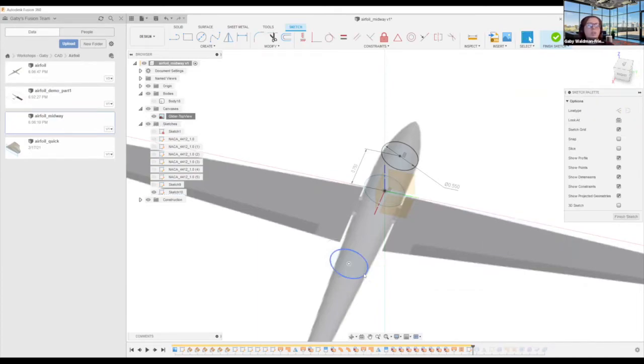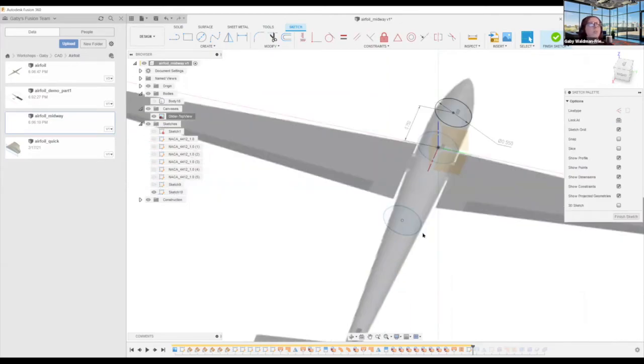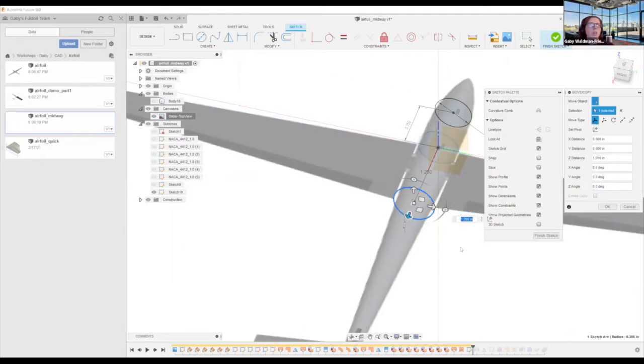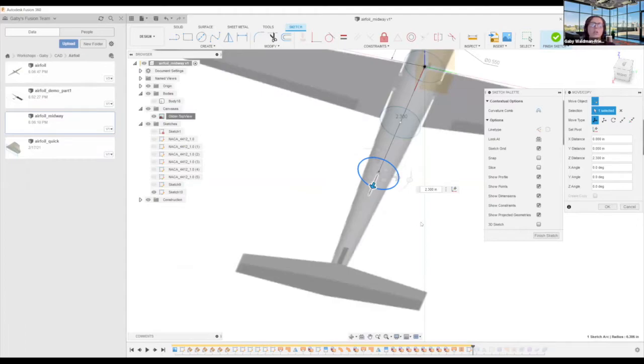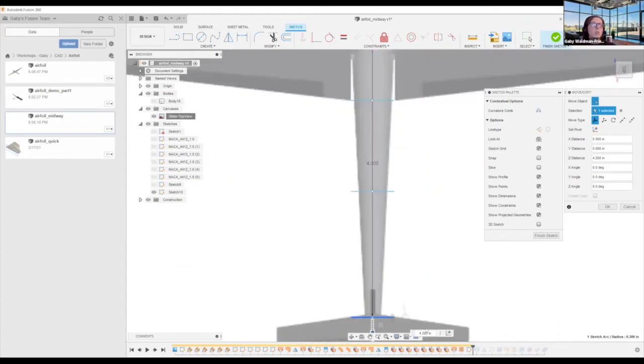And then for the last one, I'll just hit Control C, then Control V. Actually, you know what? That's a better way to do it, because then I don't have to deal with centering it. If I just hit this edge and I do Control C and then Control V, it's going to give me the same one at the same point. And then I can just come in here and move it, and then slightly dimension it later. So let's do that again. So Control V, put another one, maybe further down, and then one more. Oops, hit enter, and then one more all the way at the end here. So let's make sure those are lined up. And of course, I'll dimension each of them. Okay.